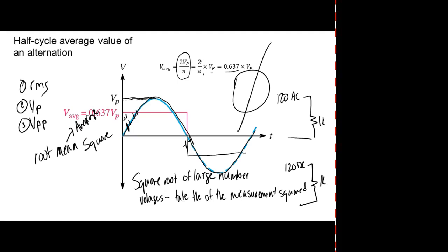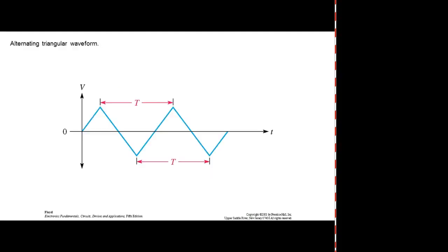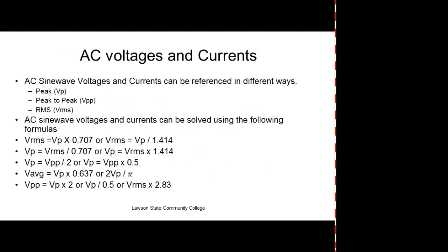Now, what did I tell you? On a sine wave, that value will always equal 70.7%. So if it's a sine wave, then VRMS will always equal V peak, and we use the positive peak, because AC has no sign, right? You understand? If you use the negative peak, you would get a negative number, so we use the positive peak. The negative peak and the positive peak are exactly the same value, they're just mirror images of each other. Times 0.707.